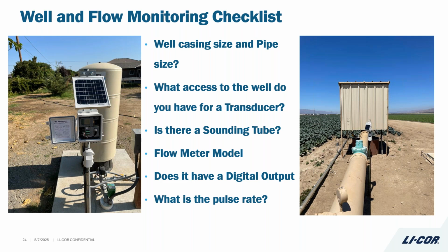Also, research and look at what type of access you have to this well to be able to get a transducer down. Is there a port on the top? Do you have a port going down the side? Are there sounding tubes in there? All of this information is really relevant to a system before you go out and deploy those. It's really important to get that information beforehand.